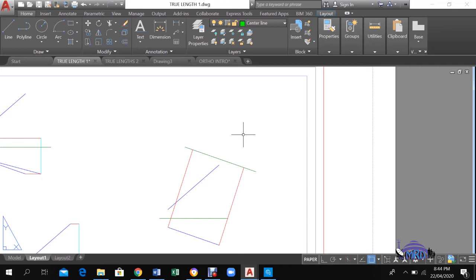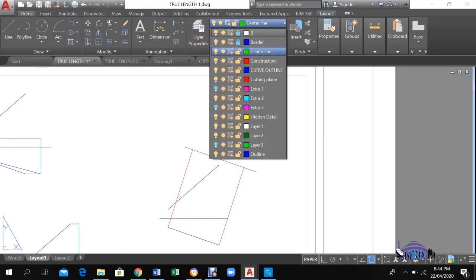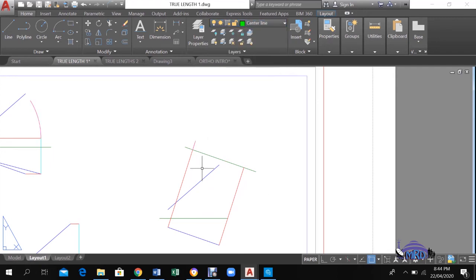Then you want to take the opportunity to transfer heights. So you want to transfer the height from the XY line to the nearest point in your front view. Once you drop in that line, then your construction starts to look like this. So that line there is equal to this height here. Then you want to take the height from the other end of the line to the XY line, and you want to mark that as well.